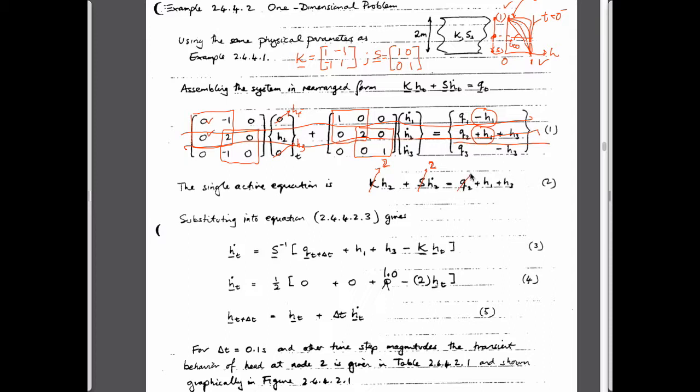This is a flux. Since we're not prescribing a flux, it's equal to 0 because mass in, flow mass in has to equal mass out as one of the internal conditions. And the values of head are the magnitudes we change it to. This is changed to 0, and this one here is kept at unity. So this is the only one that will change. And of course it's multiplied by the value of the K matrix. So each of these are just multiplied by 1s.